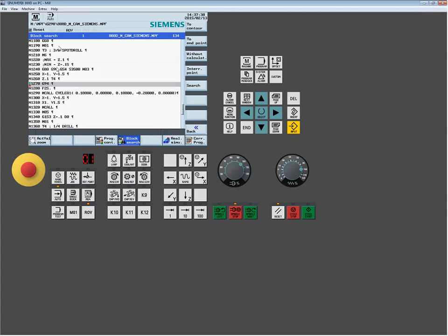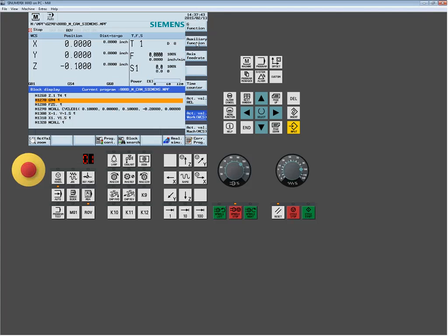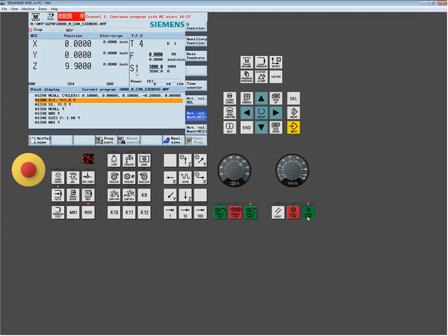And then this right here is how I physically call up my subprogram. The system is smart enough that if you simply give it the name of the file, so op1_rough, if I look back up here, op1_rough, you don't need any extensions, nothing. Just give it the name of the file, as you see it here, op1_rough. And the system will automatically start looking within its own internal memory. Wherever it finds that program, it'll start to run that program.